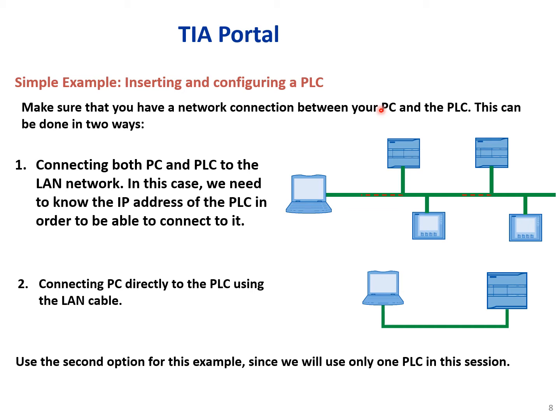Of course, now you don't have access to PLC, but you will do the configuration of the hardware, and instead of using the real hardware device, you will use a TIA PLC sim. So you will do the simulation instead of loading to the hardware.